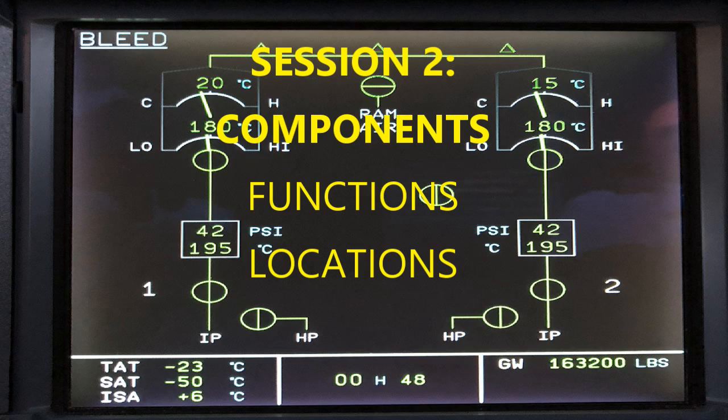Now I'm going to describe the intermediate pressure check valve, because that should be sufficient. But in cases where the aircraft is constantly changing, say it's at idle, not cruising, and there's not enough power necessary at that time, but the demand for the user systems is there, then it's going to have to pull from the high bleed, from the 9th stage of the high pressure compressor. So that's what we have.